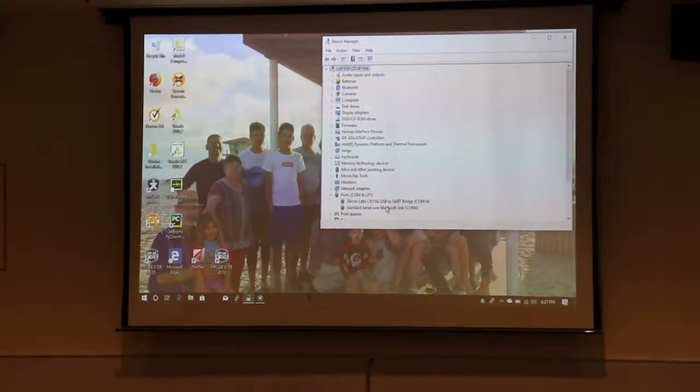So you go into the device manager, and I'm going to plug in this CP2102 device that I plugged into my board. My board's all set up for it, which is really nice. The third generation boards we used to use had a whole bunch of headers on them, but we learned we didn't really use most of those headers, so we took them all off except for the UART header, the programming header and the analog header.